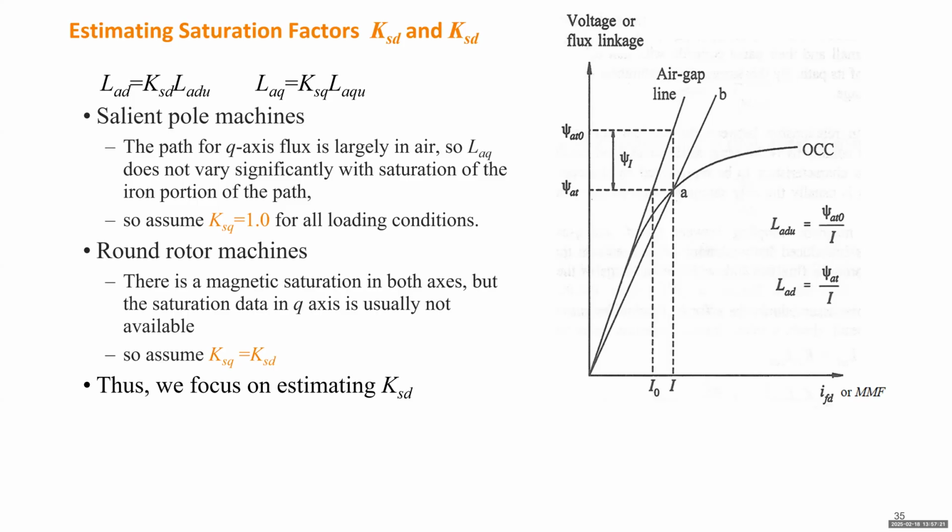This curve has almost the same slope before saturation, which means the curve is tangent to a straight line and stays very close to it until a certain point, and then it separates from that straight line. We can use this straight line as a perfect generator without any saturation. But when the load increases, the gap gradually grows. Typically we can use an exponential function to model the gap between this curve and that straight line.